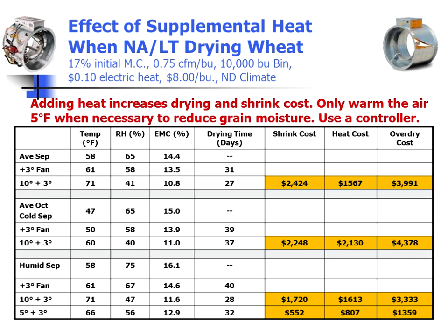moisture that we want, when we take into consideration that fan heat, it does bring us down to the moisture content that we want. If we were to add supplemental heat, and 10 degrees doesn't seem like a lot, it brings us back to 70 degrees, but drops the relative humidity down to 41%, and all of a sudden, rather than having 13.5% moisture wheat to market, we're now looking at 10.8% moisture.